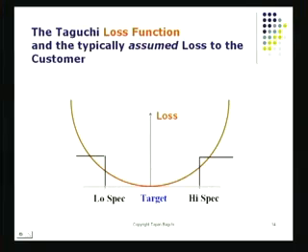But what Taguchi said is this. Let's say you've set your limits at high and low. It's not true that a shirt of this size suddenly becomes from good to bad. That does not quite happen. It actually happens gradually, and it rises by this concept of loss. Taguchi articulated that by calling it the loss function, and I'm going to show a little formula for calculating it.